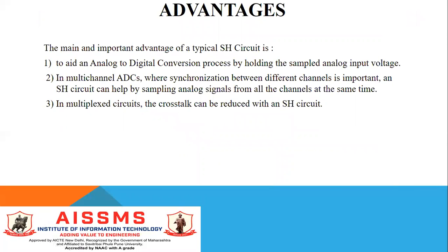The advantages of sample and hold circuit: it aids an ADC process by holding the sampled analog input voltage. In multi-channel ADCs, where synchronization between different channels is important, a sample and hold circuit helps us by sampling the analog signals from all channels at the same time. In multiplexer circuits, the crosstalk can also be reduced to a great extent with a sample and hold circuit.